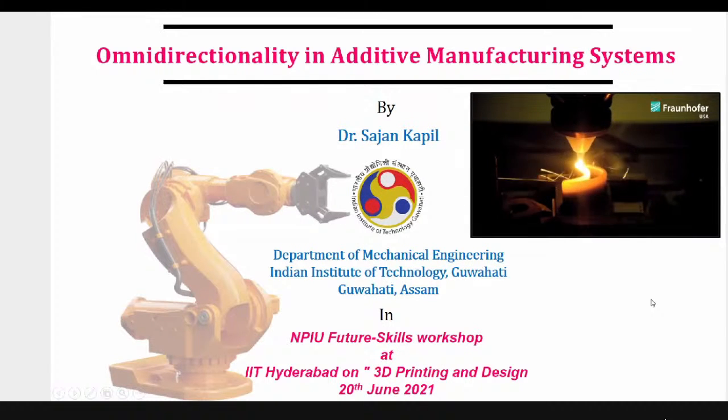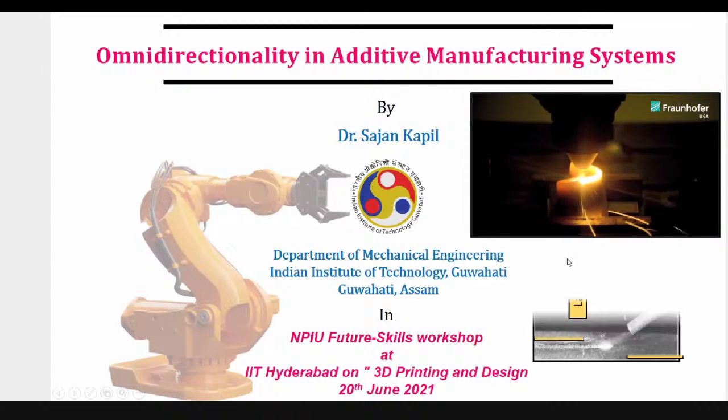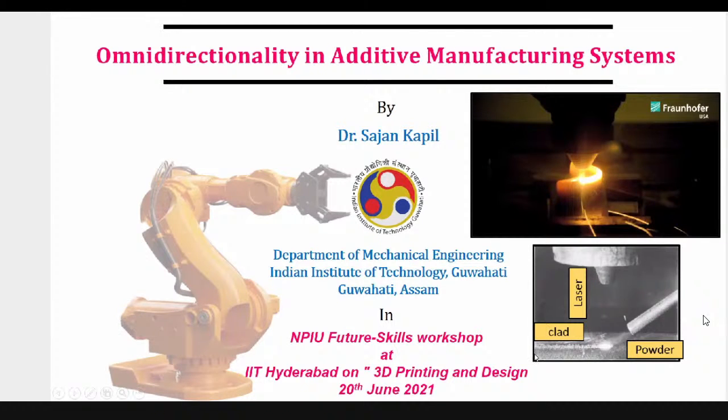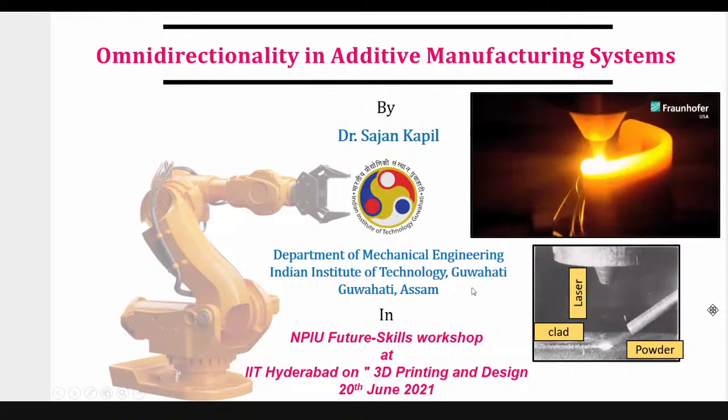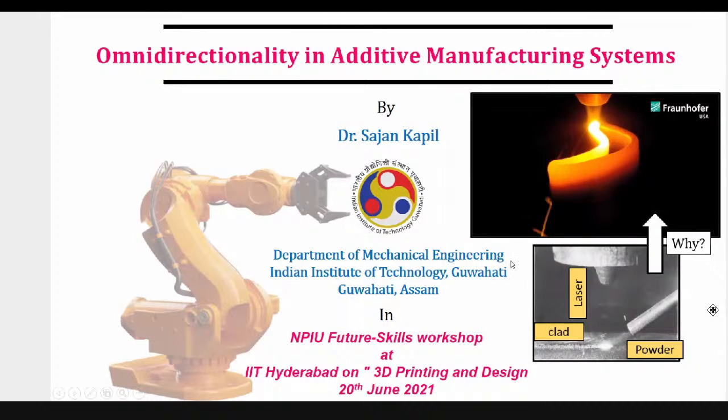Now there is a question: was it the same way when it was invented? It is not. When it was invented, it looks like this. I have already mentioned in the last lecture, Professor William Steen, when he invented the laser cladding process based on powder, the process looks like this. It used to have a laser at the center, which is a CO2 laser, not visible to us because it's in a different wavelength. And this is the clad path, and you are just feeding the powder from the side. Now, such a simple system has really converted to such a sophisticated system. Why? So that you will be able to have an answer. And this is about only DED.